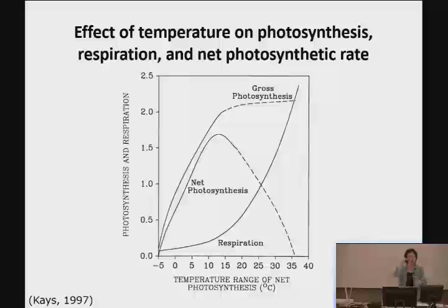So the leaf temperature is important, but which leaf to measure to represent the entire greenhouse is always the question and always the challenge. And when we do the greenhouse lab in April, we all go out with a bunch of sensors and measure the temperature distribution in the greenhouse. Hopefully you see the large difference in temperature, top of the canopy, middle of the canopy, north side and south side. And you can actually quantify that.